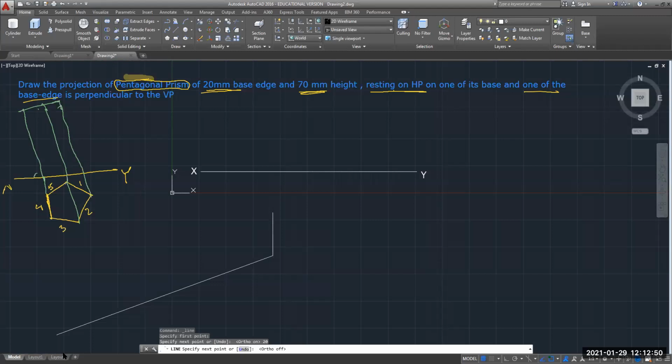Okay, let's come back to our drawing. So if we want to draw an angle that is 108, so 90 minus 108, it will be 18 degrees in negative direction, and the length we want to move is 20. So at the rate 20, and angle is minus 18. Let's see whether it is working or not. Yeah, it has worked.